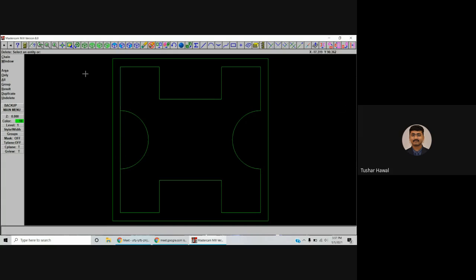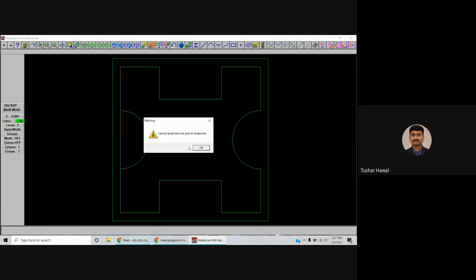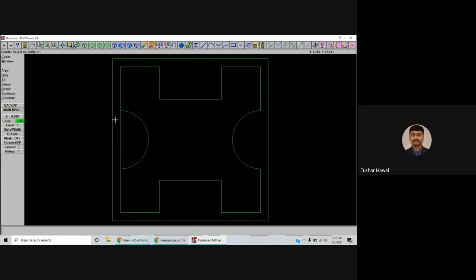Okay, so this is the line to be broken yet into two pieces. This line at this point, line at this point is already broken. So let me use the delete option, delete this and this. So we are very much near to the geometry. We'll just complete the filleting option, modify, give the fillet of radius. What is the radius? 10 at this point, this point, this point, and this point.